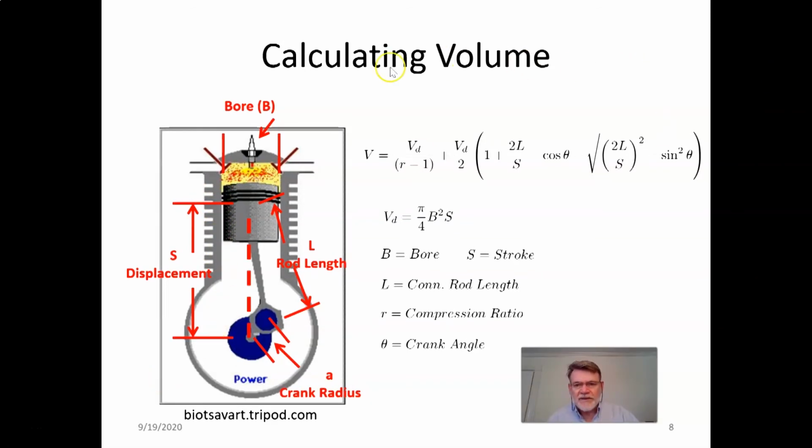So this math here comes from the calculation of the position of the piston with respect to the crank angle. Basically, it's about drawing a crank circle and resolving for the piston pin distance from the crank center, and crank angle theta.